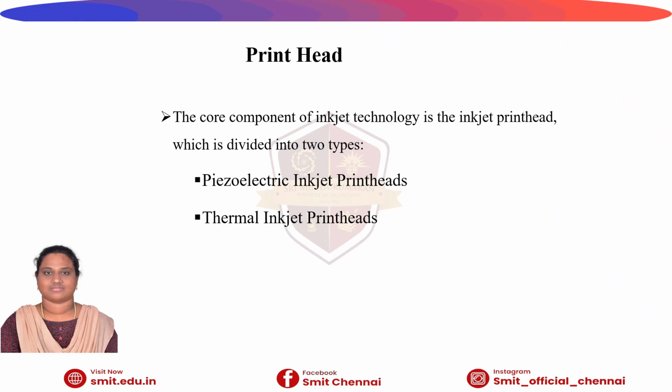The first one is piezoelectric inkjet print heads, which use electrical deformation of the piezoelectric element to eject droplets, and the next one is thermal inkjet print heads, which use localized heating to form vapor bubbles that force droplets out of the nozzle.